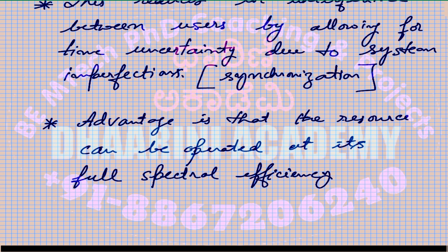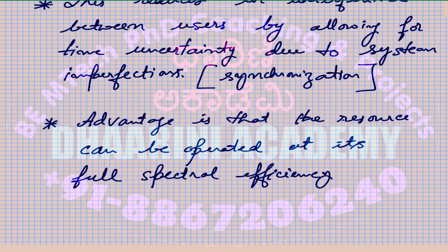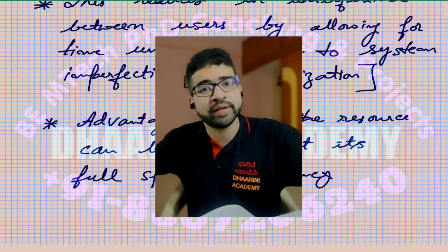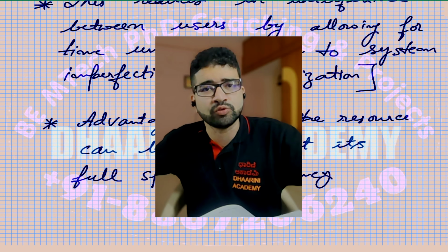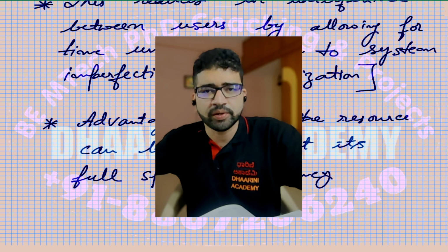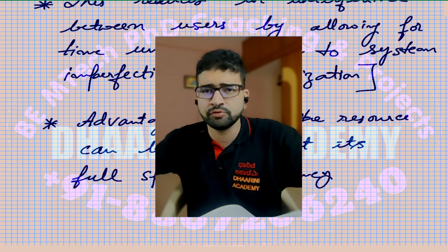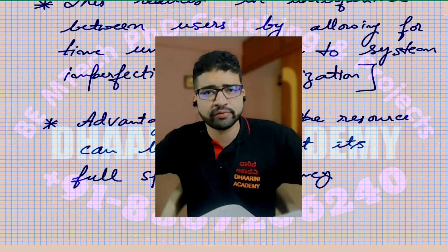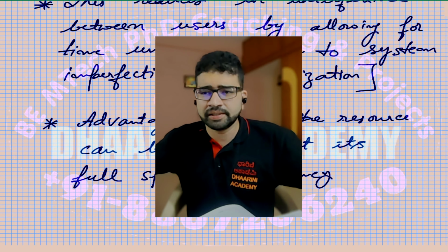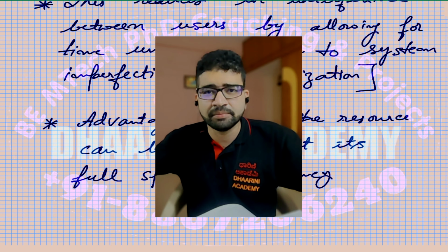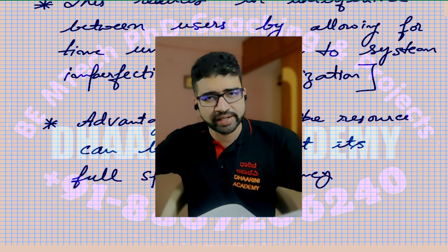In other words, if you are talking about FETs or BJTs, you can make them operate in the saturation region, where the highest power gets used for a given device. So in TDMA, the region you prefer to operate any device in is the saturation region. In the other case, you may have to go for the active region or turn on and off in between, and save some power over there. But that restriction is not there in TDMA, which acts as an advantage of TDMA over FDMA.